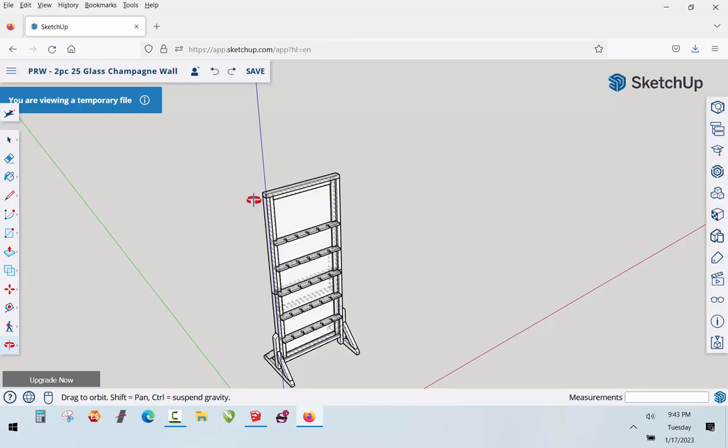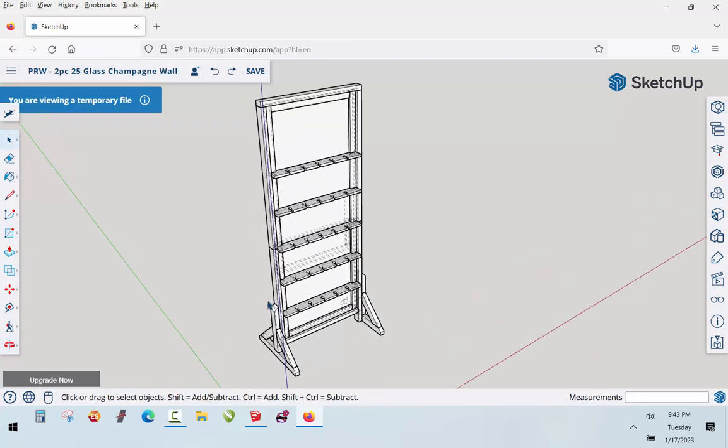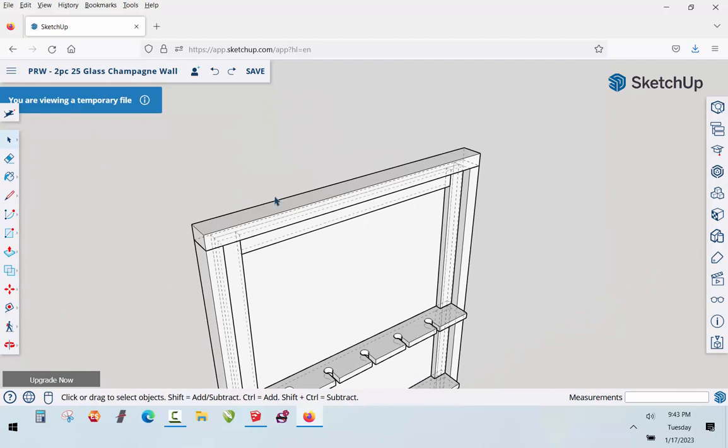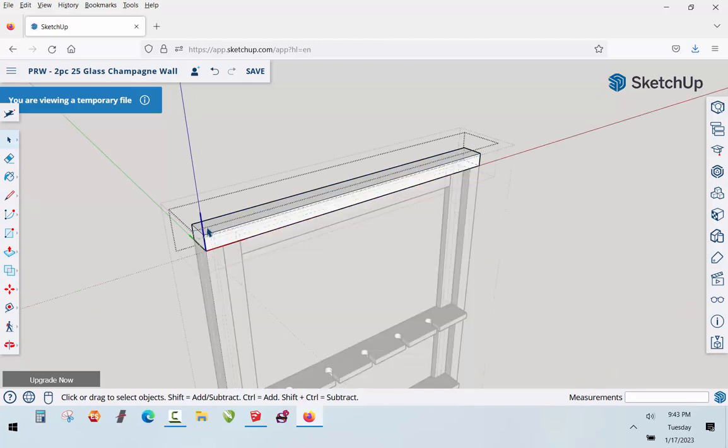abilities come, of course, you can use SketchUp to do your own drawings or modify our drawings. For example, just to show you how easily you could do something, if we wanted to adjust this top piece of wood here, we could just double click on it, and then we could hit the P key on our keyboard, and we could lengthen it, or we could shorten it. We could click on this face.